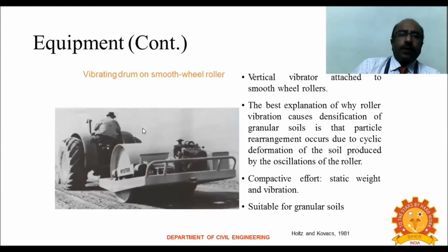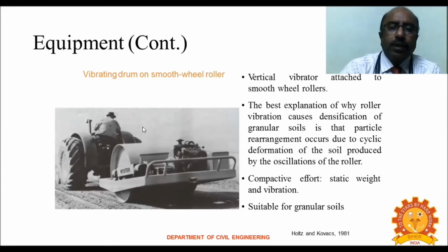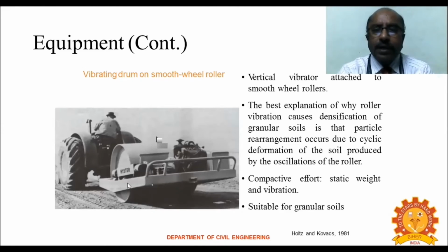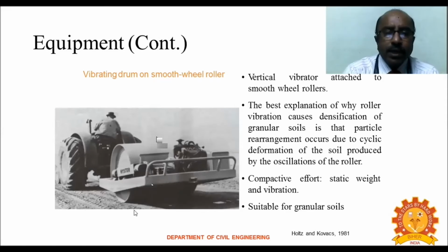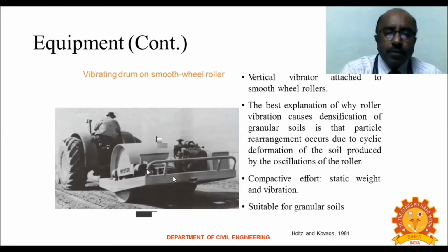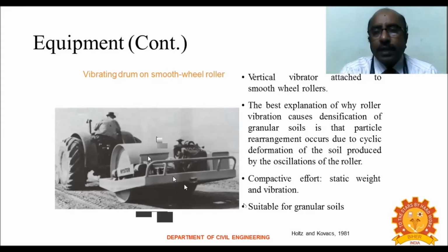Also we have the vibrating drum or smooth roller, where along with the weight or static load, we are introducing some amount of vibration, and because of the vibration, the compaction is achieved very quickly. Because if you use a plain smooth roller, it will take a longer time, so we are introducing this vibration.